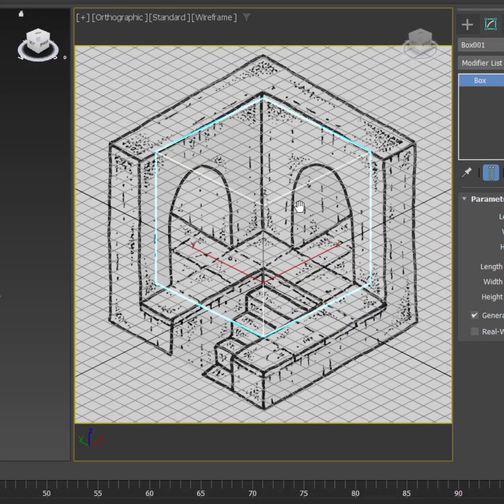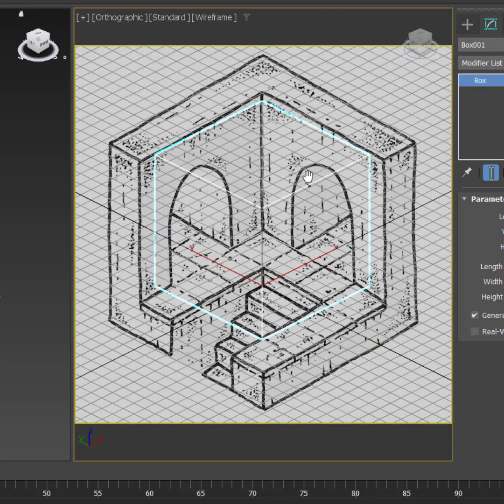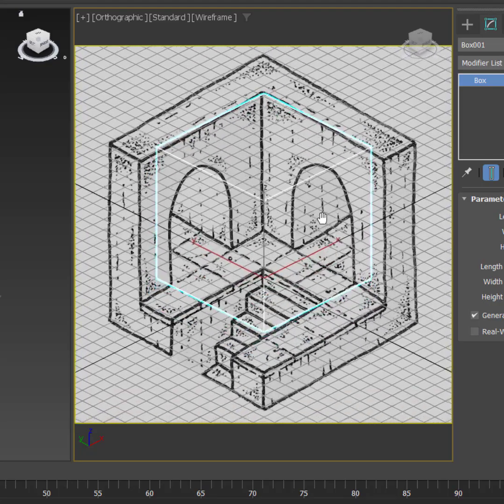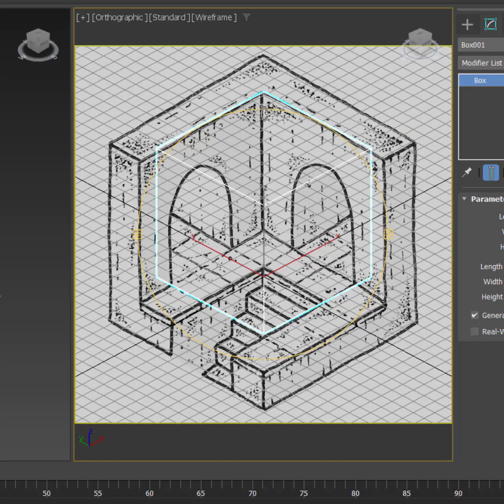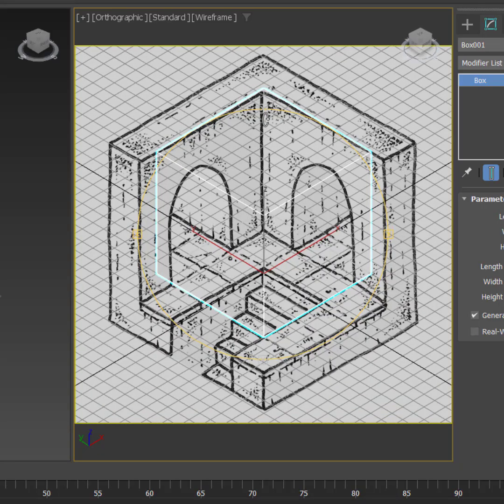Okay, so that's how we are aligning this. We are aligning it by view, not by movement. Okay, as you can see, the box is still at the center of 3D space, and that's very important. And here I am positioning it to be aligned with the reference. Okay, next thing, I will press Control R. Control R is the view rotate. The view rotate allows me to rotate the view or tilt it to align further my object.